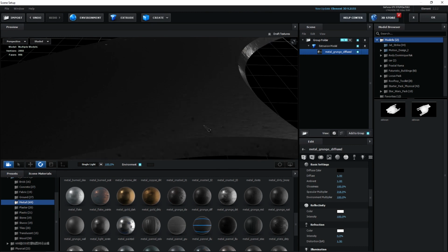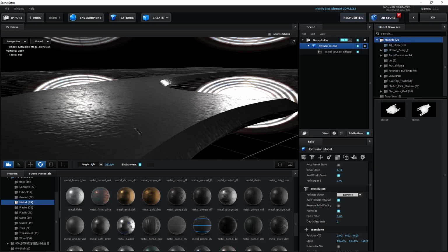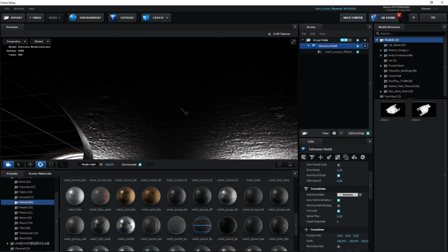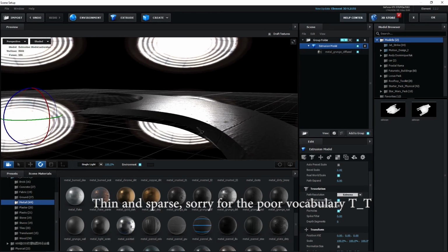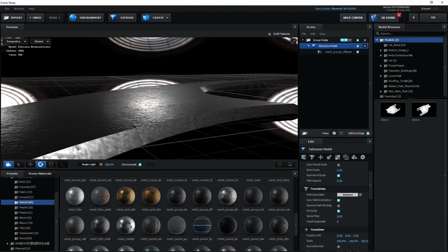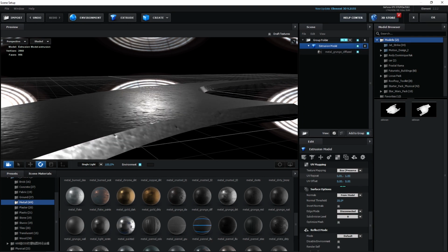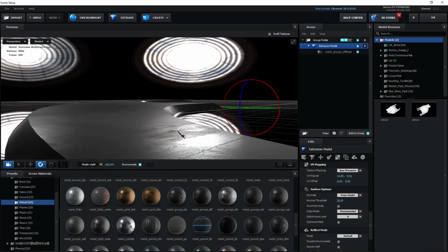Okay, so we can go to the UV settings because this UV map is not dense enough. All right, you understand what I'm talking about? It's not dense enough, so we need to repeat the map a little bit higher, and that way we can get some smoother and more details in the object.